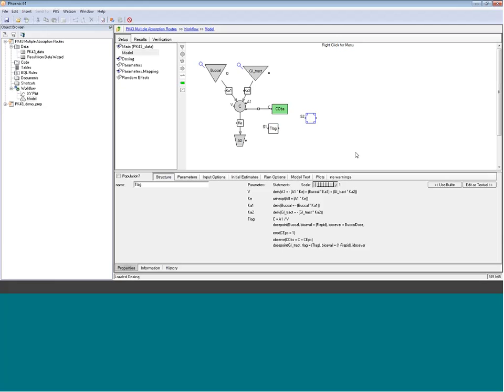And then I can insert a second parameter, and we'll call this F rapid. One thing to be mindful of when using this graphical mode or PML is that it is case sensitive. So this capital F is important, and then the lowercase for the rest of the parameter name. Okay. So at this point, I've built my model.